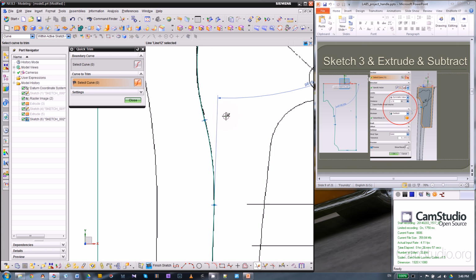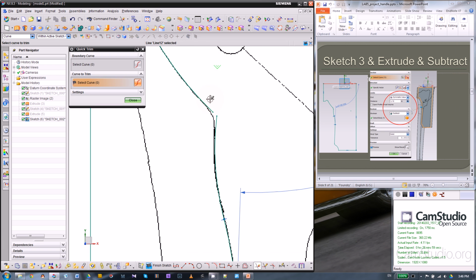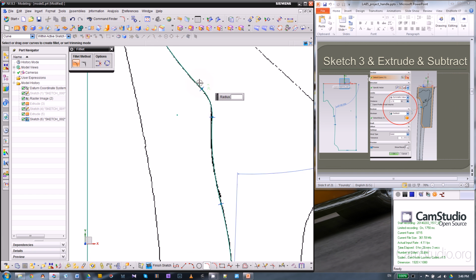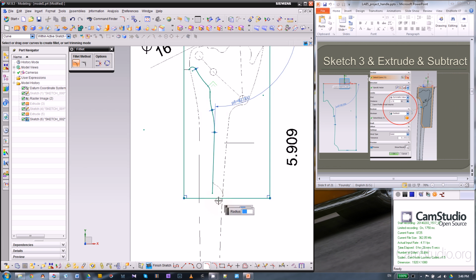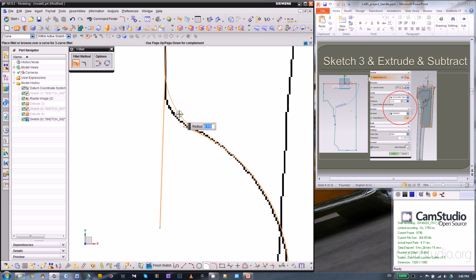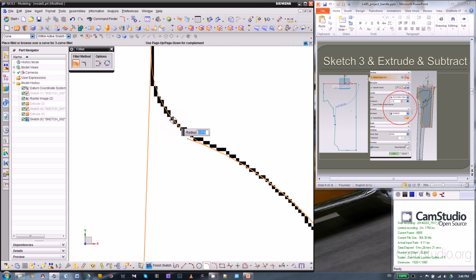We can trim off the top, then come back, put the fillet back in. That'll be the last arc, 3-point arc, on curve, end point, looks like this, and then fillet to connect the two curves.